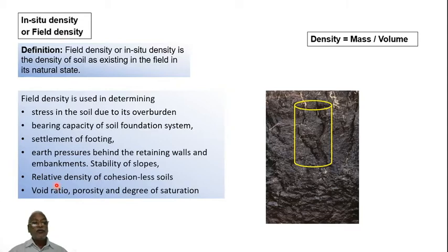Also, relative density of cohesionless soils is found by knowing the density. Other applications are stress in soil due to its overburden, bearing capacity of the soil foundation system, settlement of the footing, earth pressure behind retaining walls, and stability of slopes. There are many things in which we need to know the density of the soil as existing in the field.